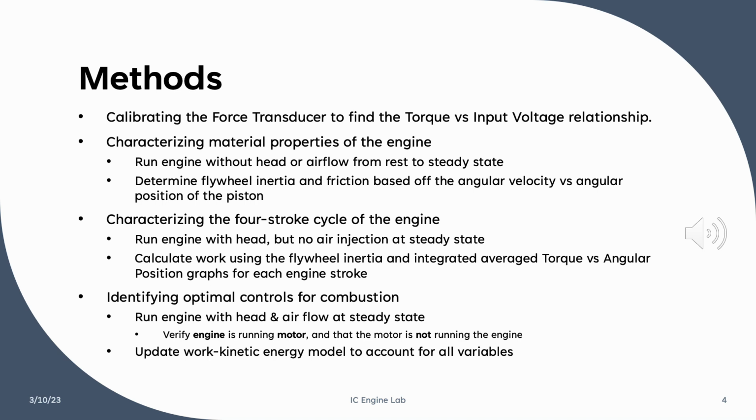The angular velocities and average torques for each of these strokes will be found, which can help to then calculate work. The work is calculated using the flywheel inertia and integrating over the average of the torque versus angular position graphs for each stroke.